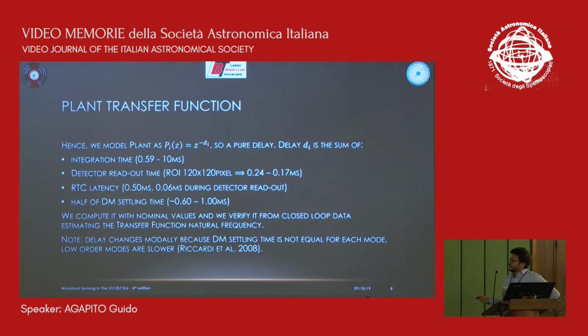What we can say about this delay is that it is the sum of several terms. For sure the integration time, but even the readout time, the latency of the RTC, and the DM settling time. We have computed the nominal values during the design of the system, and during commissioning we have verified through tests in the real system the values that we get.